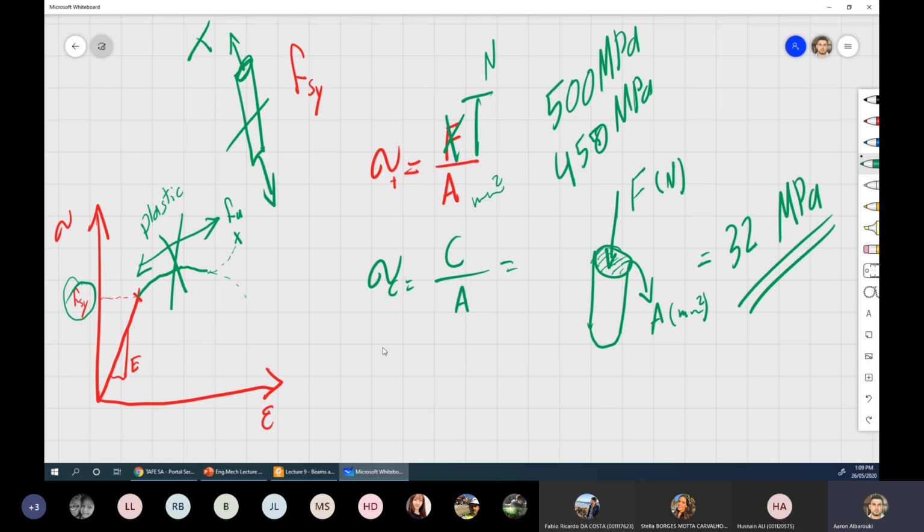So this is just generally speaking. These two, we call them normal stresses. Why normal? Because look at them, either compression or tension. If I draw this from the side, this is the sample, and this is the force, either compression or tension. Look at it, it's at 90 degrees to the surface. They are normal to the surface. Normal means perpendicular. We call these the two types of normal stresses.